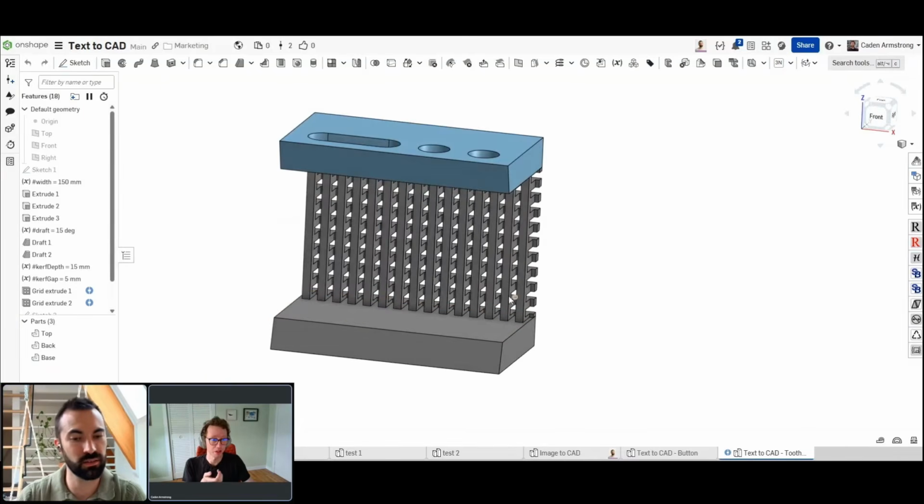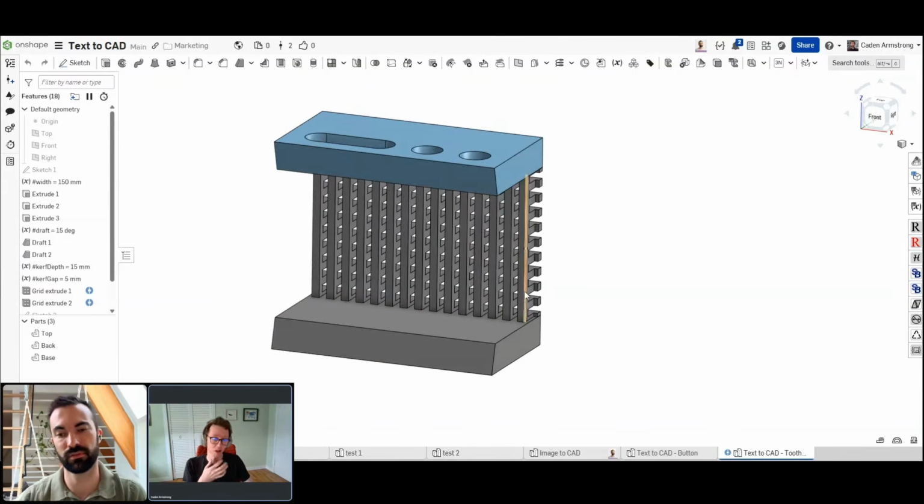When we reviewed the design, we looked at this bottom and I realized we shouldn't put kerf there because of this reason. We can look at this design and go, okay, now that I have it, I can make decisions. Realistically, one inch up from the bottom there should be no kerf, because when I go to manufacture it, I'm going to put dowels there. So it solves the problem of cleanliness, but it also gives me manufacturability. Maybe that wasn't there in the first prompt, but being able to highlight that section and say, okay, remove it from here, would be more valuable than having to redo my whole prompt.